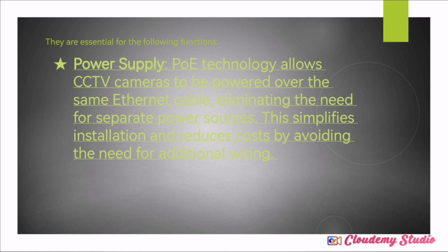But what you should also know is that the cameras differ. There are some cameras that are non-PoE, meaning they still need a charger. A PoE setup only works when you are using PoE cameras as well as the PoE switch. But don't worry about that. At the moment, I just want you to understand the function of the PoE switch and a non-PoE switch.